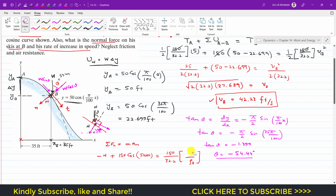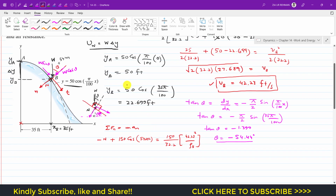So now v_B is 42.23 square, and we have to find the radius of curvature, and we know the equation for the radius of curvature from the kinematics. So let me write that equation. The radius of curvature will be equal to 1 plus (dy/dx) square, to the power 3/2, divided by the absolute value of d square y by dx square.